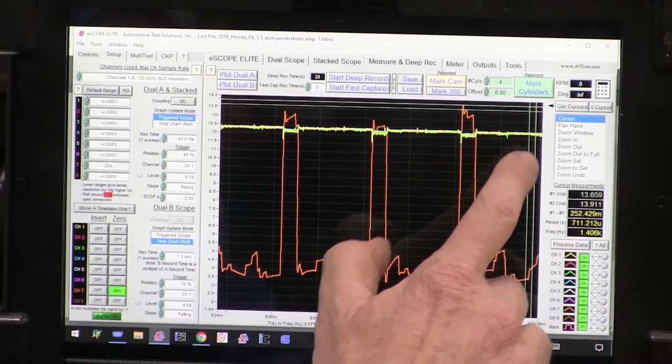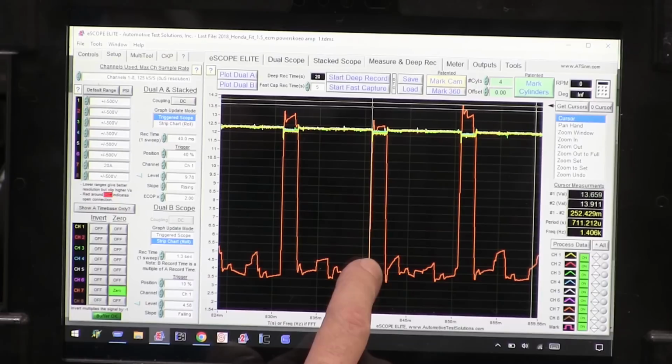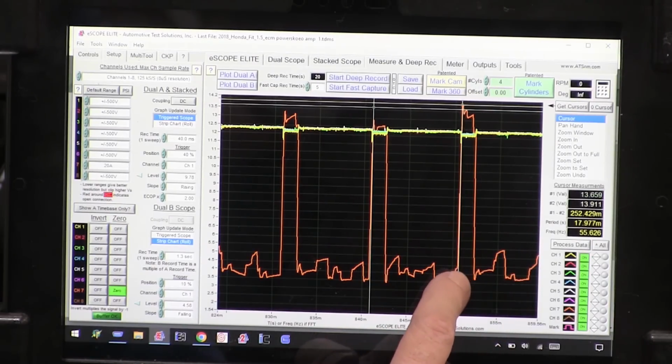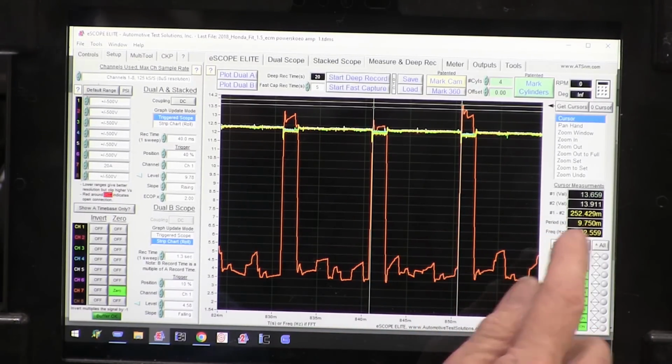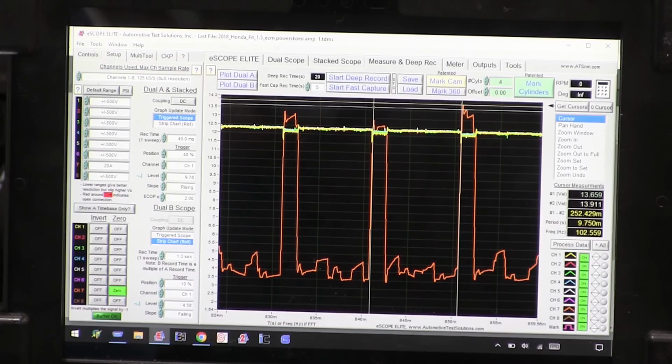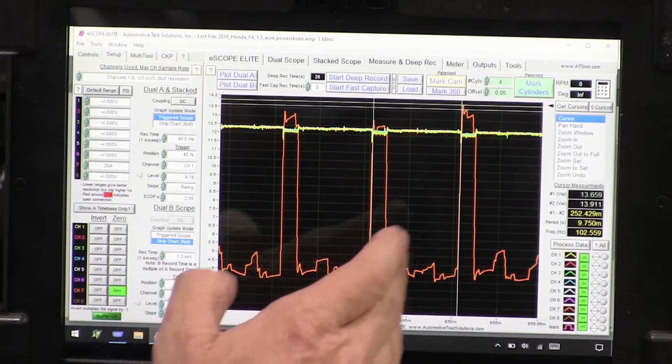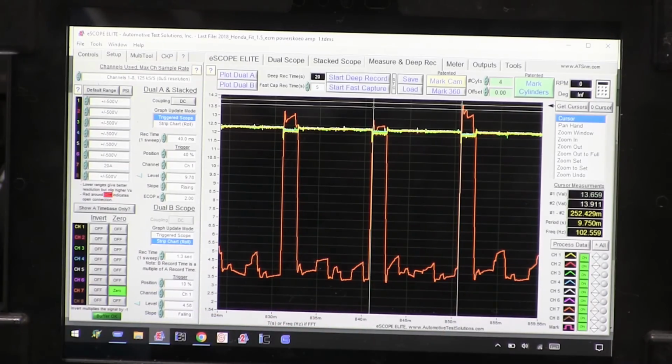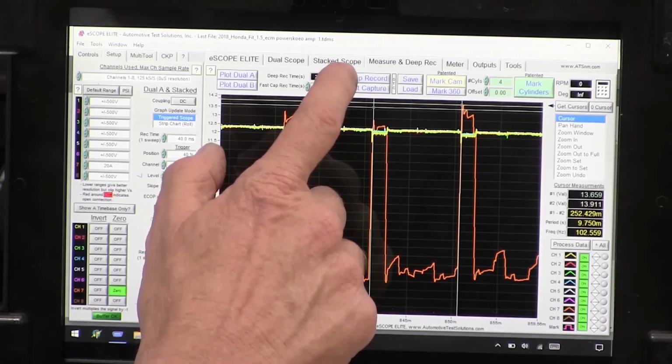And again, we can measure these ones over here that are different than what I just measured. And they come up at about the same, 9.7 milliseconds. So this is something that's being controlled, like something out of the computer. Now I'm not sure, maybe that's pulsing the tranny, or maybe that's because I have a computer problem, because we're looking at this computer because we have a problem. But the step 1 that I've got to start with is checking powers and grounds for a drop that's big enough to cause me a problem. Now is what I want to do.